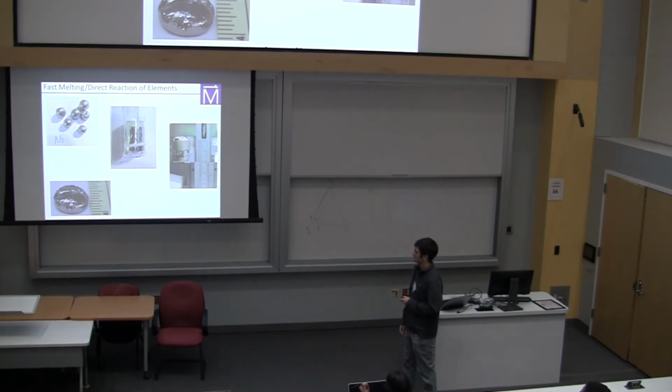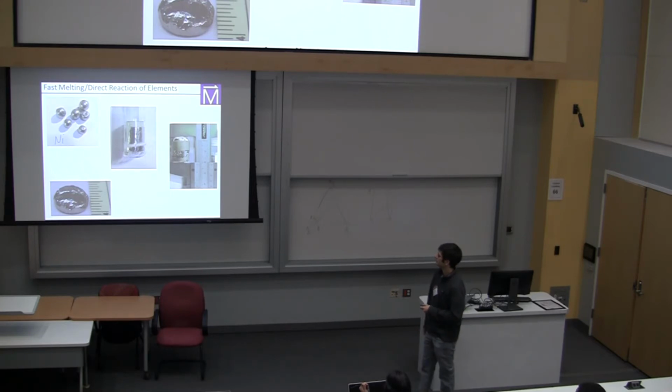Of course, in this case, this is touching the quartz, so don't go above 1200. And in the end, you wind up with a nice precursor boule that you can use. One neat thing that I like to point out here is that this process also somehow produced some little single crystals of nickel sticking out in that void there.